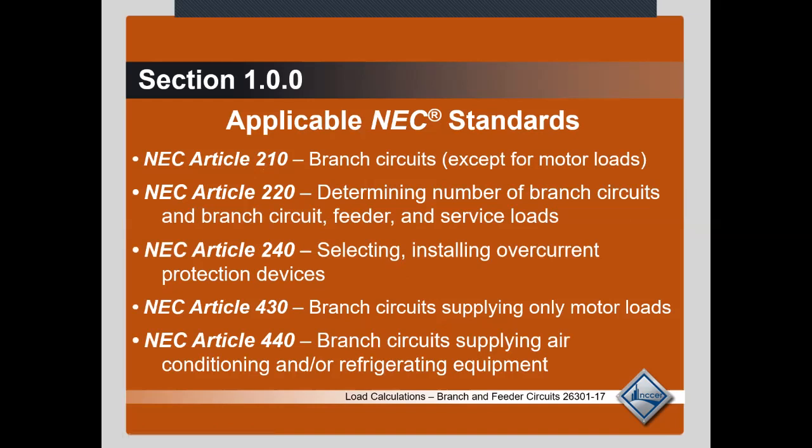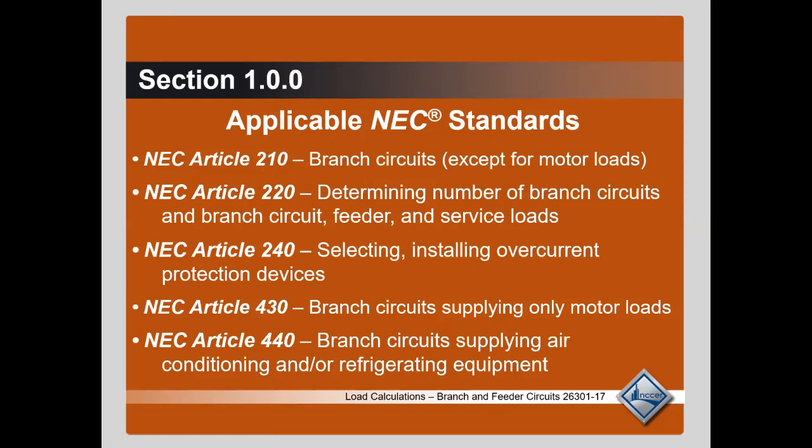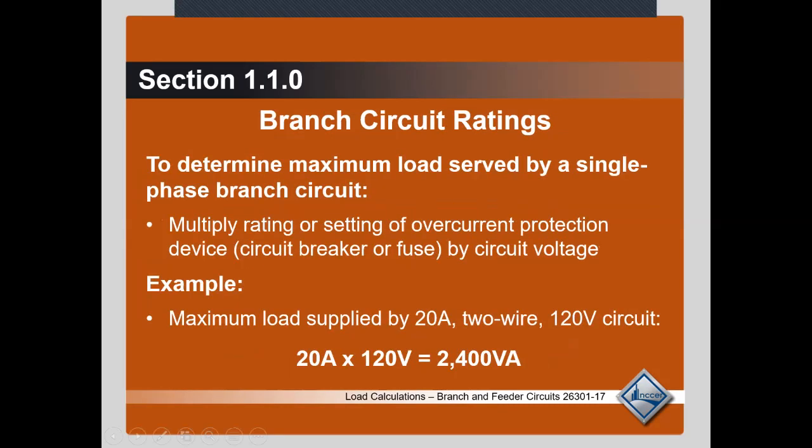Applicable NEC standards: 210, 220, 240, 310, 430, 440. So those are all applicable standards and deal with loads. All right, to determine the maximum load by a single phase branch circuit, you multiply the rating of the breaker by the circuit voltage.